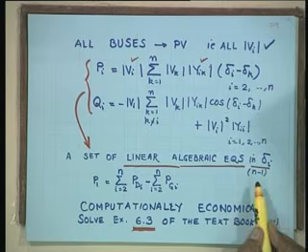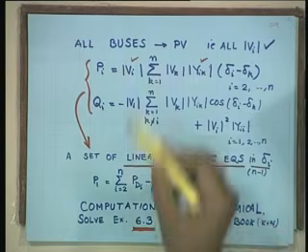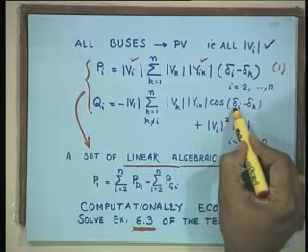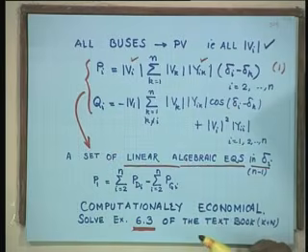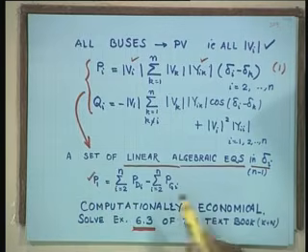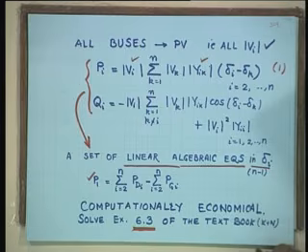So, once we solve the first equation in delta and substitute here, we get Pi and Qi both. And once you get Pi and Qi, you can find out the slack power P1, which is unknown. So, slack power is known. This is a computationally very economical way of solving SLFE, because they become linear equations. In fact, we do not have to go for an iterative solution. It gives you a closed form solution, or use Cramer's rule or whatever, and you can straight away solve it.